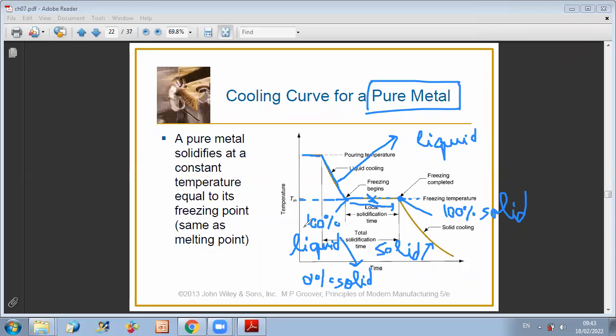So this energy, instead of giving you a change in temperature, will destroy or form bonds depending on whether you are going from solid to liquid or from liquid to solid, etc. So in this phase, we say that the exchange is in form of latent heat. And we can express latent heat and sensible heat. We'll see together what the equations for latent heat and for sensible heat are.